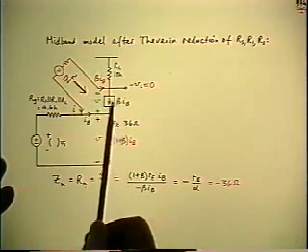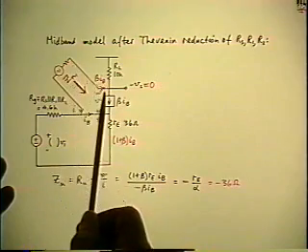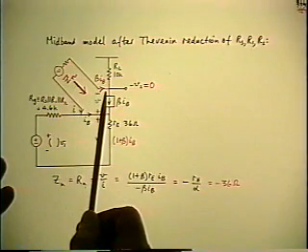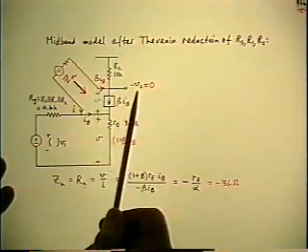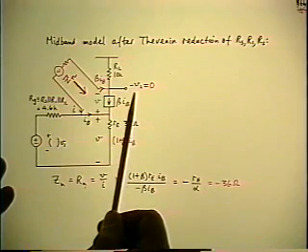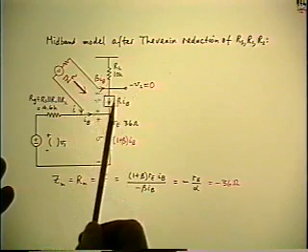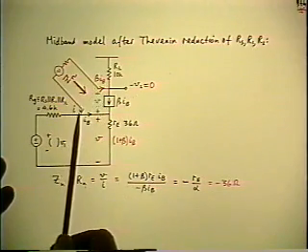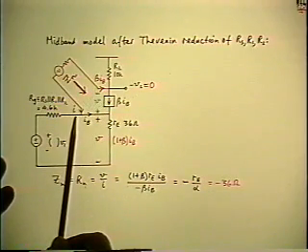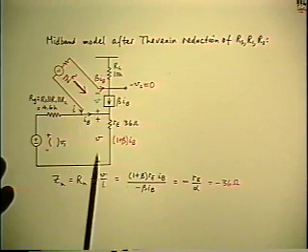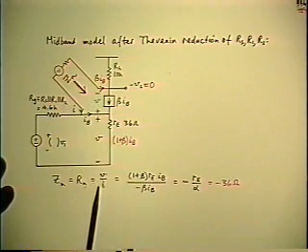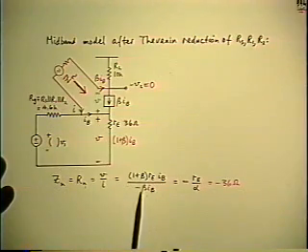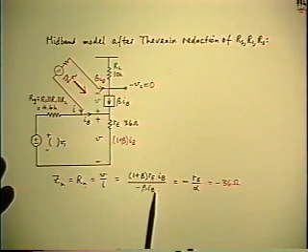What it does say is that the collector current is equal to the current to the second source, because there's no current in RL because of the null. So the current in the second source is equal to beta IB, but that current I've already defined as minus I. So in the denominator, V over I that I'm trying to calculate, the I I've replaced by minus beta IB.